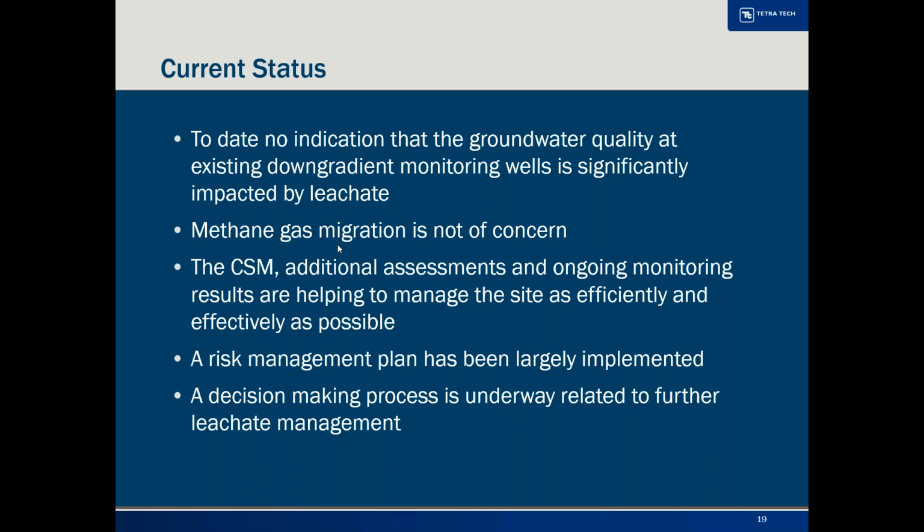Partially due to the intercepted trench, the passive venting trench for landfill gas, we don't have much of a methane gas migration issue. We only find one concentration typically that is outside the trench that is higher than the trigger value in the landfill standards for landfills, and that is an isolated location. The conceptual site model and the additional assessments that we've done recently have helped us manage the site as efficiently and effectively as possible. And the risk management plan has been largely implemented.